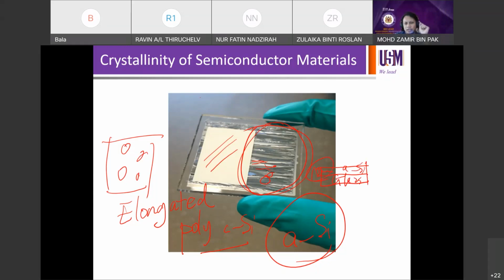So originally deposited as amorphous silicon, but because my PhD was on polycrystalline silicon solar cells, I used laser to crystallize this amorphous silicon into polycrystalline. The laser scans like a laser beam, like we use a 3-in-1 scanner.